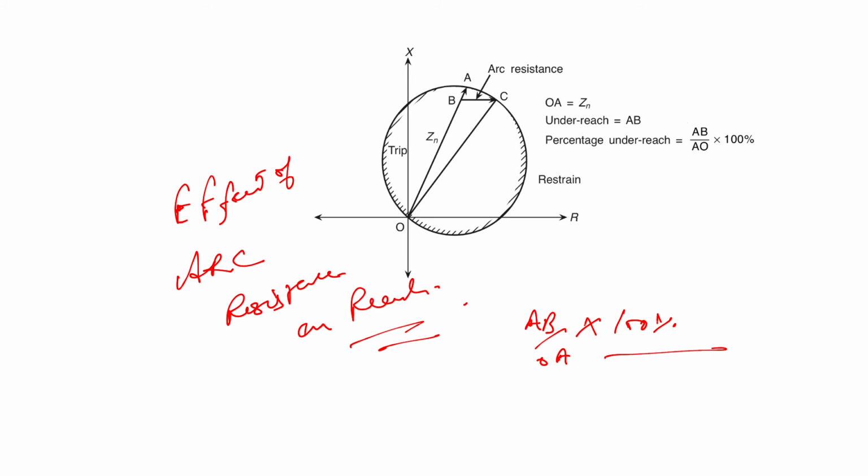However, the simple impedance relay also suffers from underreach due to the fault resistance. If we compare the underreach of the two relays for the same fault resistance, then we find the percentage underreach of the Mho relay is slightly more than that of the simple impedance relay.